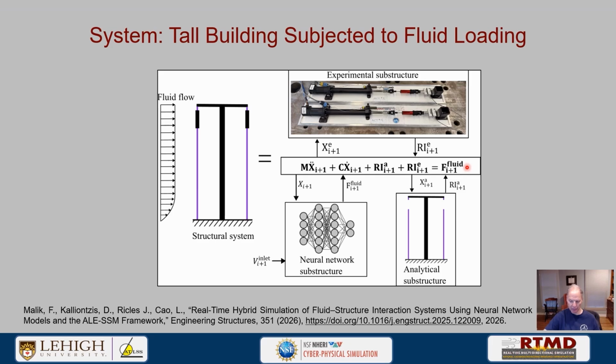We also know the displacement, so we can impose those over the period of the time step, and near the end of the time step we recover those fluid loadings in that displaced position and then integrate the equations. So that's described in more detail in this reference here.